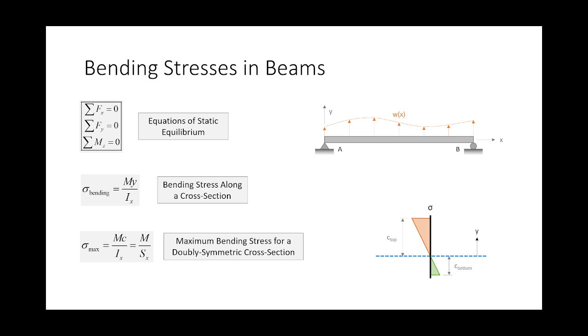So what do you need in order to properly handle bending stresses? Well, first off, you need to be able to construct shear and moment diagrams in beams. You just have to. It is very typical in mechanics of materials problems related to bending that you are given a beam subjected to a point load or a distributed load or whatever, and the question is, what is the maximum bending stress due to said load? So you have to be able to compute support reactions and draw a shear diagram, draw a moment diagram, etc. Okay? So that's the moment.